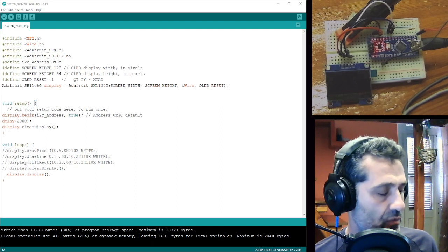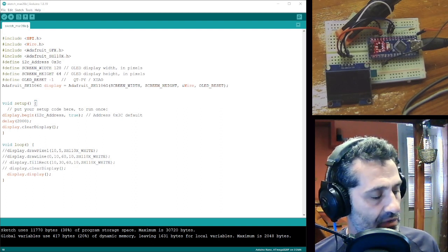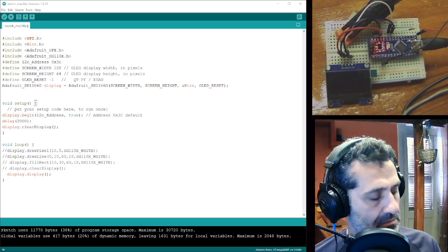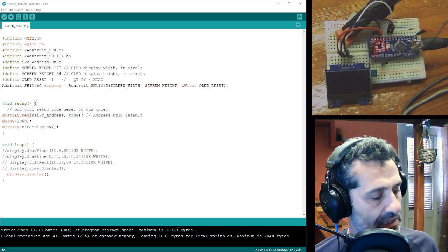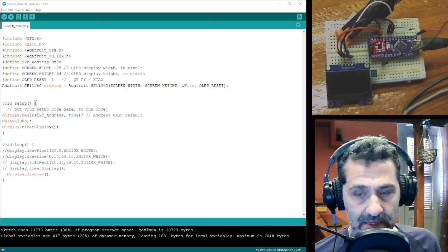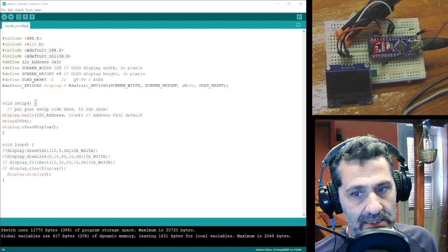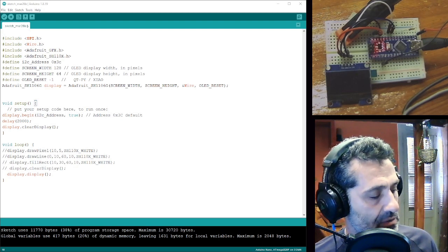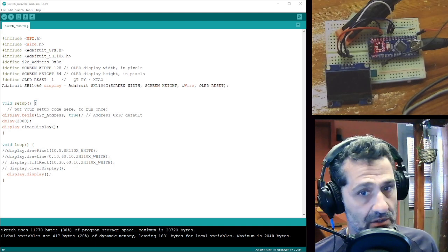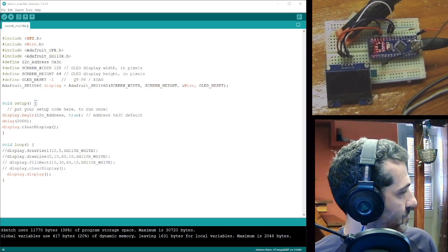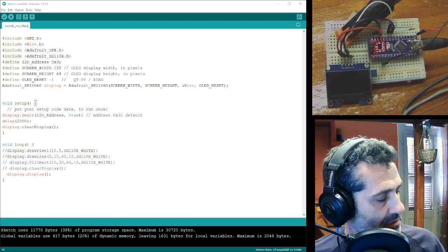Internally the Arduino has a very big resistance in series with the analog in, but it doesn't do any harm to add another resistor ourselves. So that's what I did.